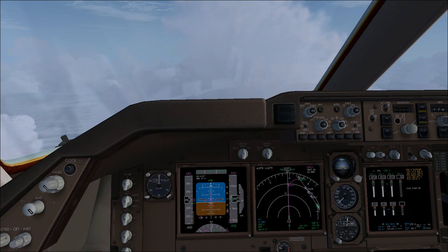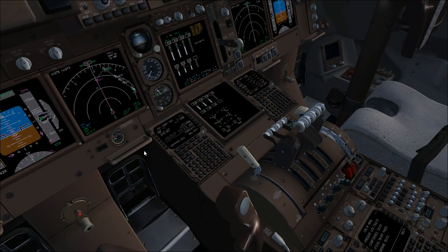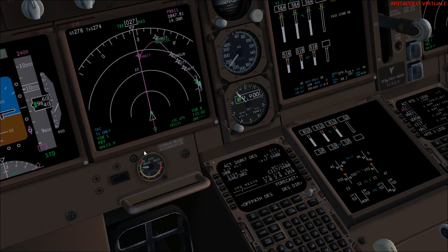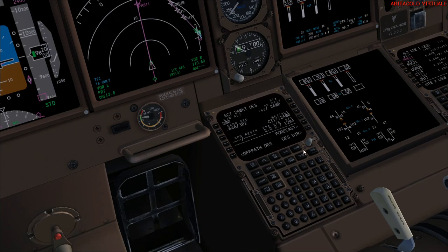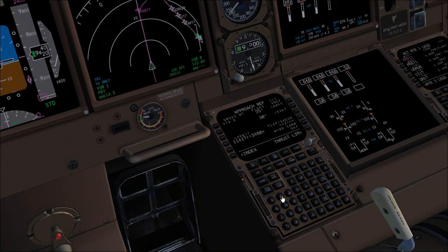Okay, here we're back. As you can see, we have just started descent. The aircraft has commanded vertical speed. At the second point, we have the deceleration to 245 knots. After the briefing, we have to select the approach speed. We expect to have 98.8 of fuel during landing, so 98.8 summed with the zero fuel weight of 178.9 gives us a 277.7 expected landing weight.